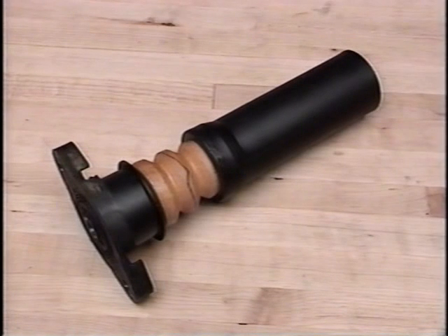When replacing rear struts, you should also install 1992 strut jounce bumper assemblies on both struts. Newly designed jounce bumper service units help prevent strut noise from being transmitted into the car body.